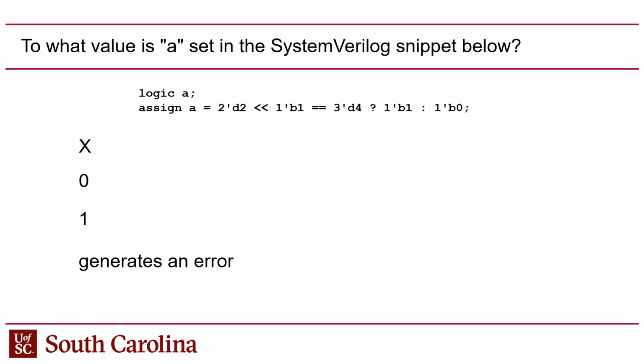It's going to compare this, and then it's going to evaluate the ternary to 1 if it's true or 0 if it's false. Now this is redundant, by the way, because if I had just put in the condition by itself, it would already evaluate to 1 or 0, because that's how conditionals in Verilog evaluate to a single bit. Having this ternary operator is just redundant. But it's still valid, right?